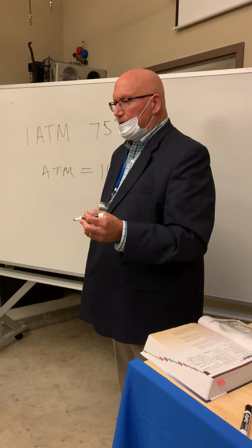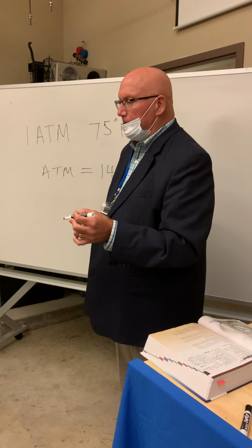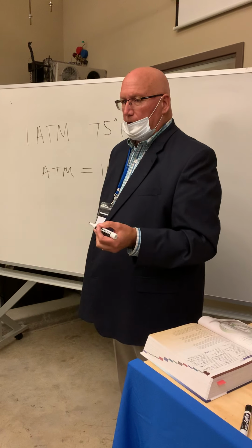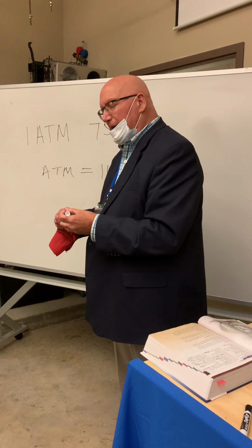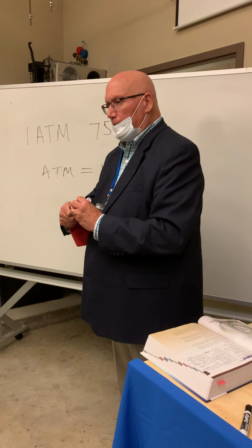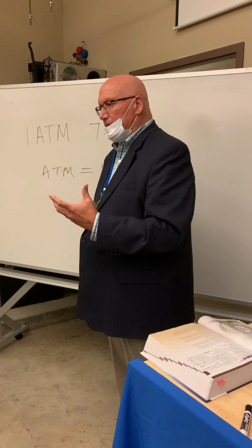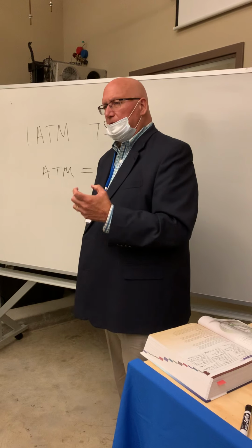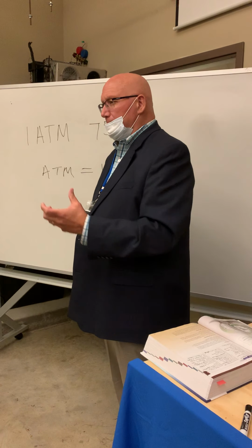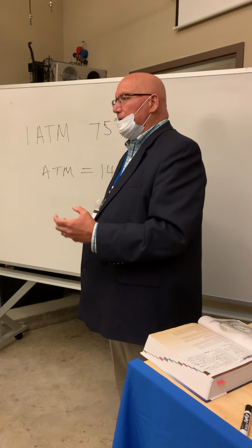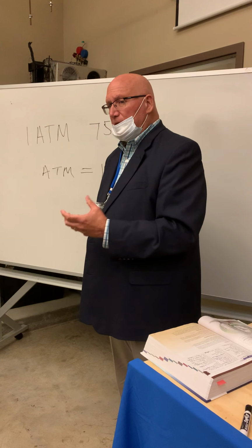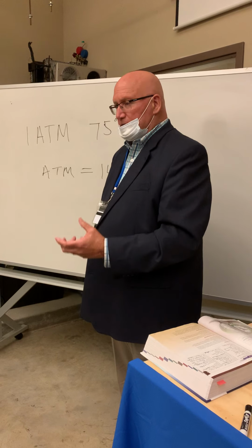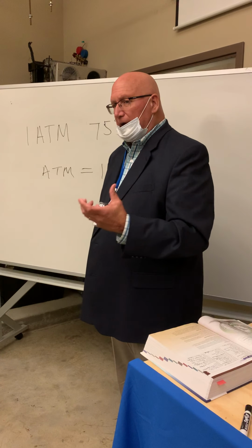A lot of times technicians will round that to 15, or you can say 1 atmosphere. Later when we start talking about a vacuum, that's going to be important because it really explains what we talk about when we say we're going to vacuum a system. What it means is that we're going to take the pressure inside that sealed container to less than atmospheric pressure. That's what a vacuum is.